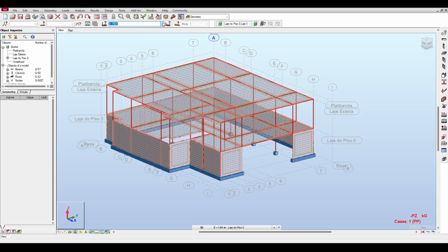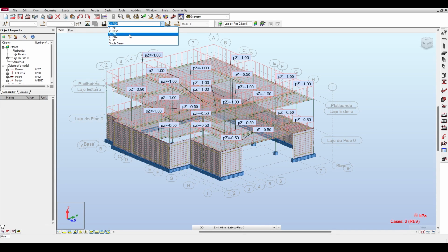And then the load case for dead load maybe, and another case for dead load, another case for dead load, and a case for live load. Why doesn't he, for example, put the self-weight in one of those dead loads? There is a reason behind that, and I will mention this later. This is actually a very good approach by him, and I will explain to you why this is the best way of making load cases if you want to make a modal analysis. So all in all, we have case number one, which is the self-weight, 3 cases which seem to correspond to dead loads, and 1 case which seems to correspond to live load.